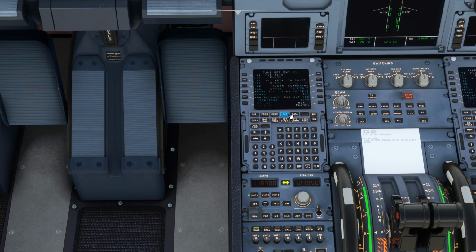This is regarding the MCDU. So we have done all, the flight plan is there. We have weight and balance. We have our init A and init B. We have our performance V1, VR, V2, the flaps and everything, and flex temperature, engine out, thrust reduction altitude, transition altitude, everything done. So this was the tough part and the boring part.